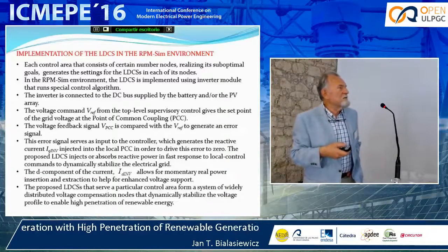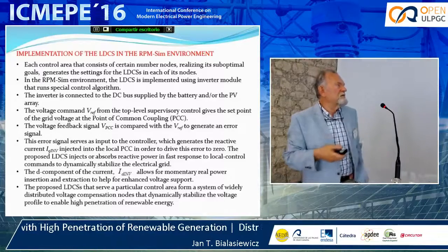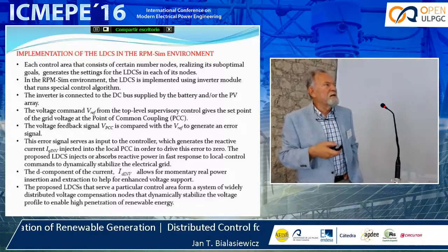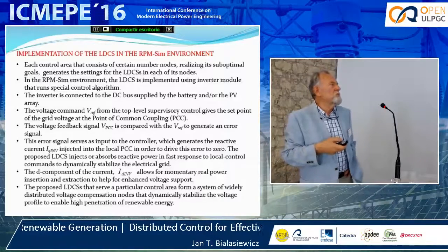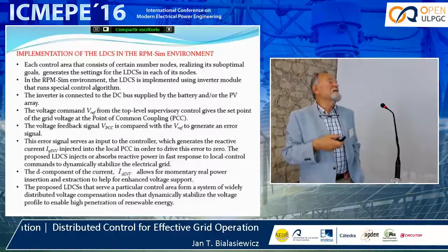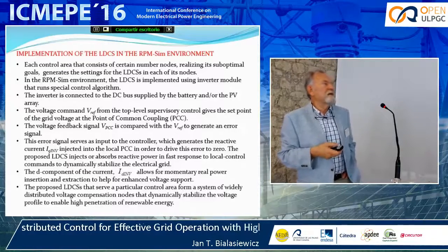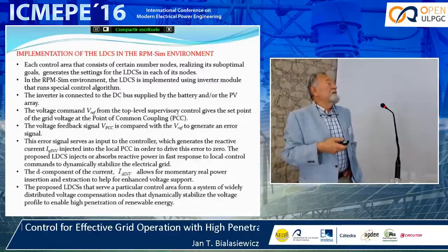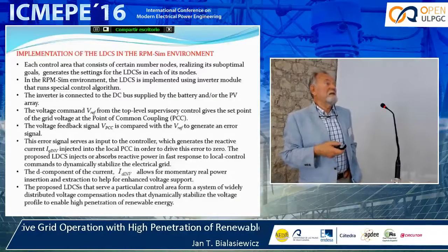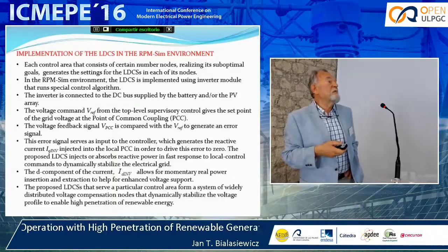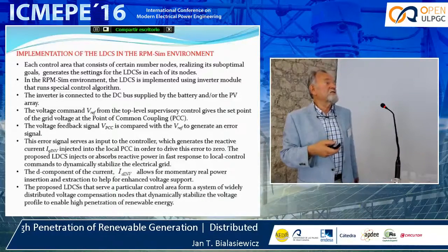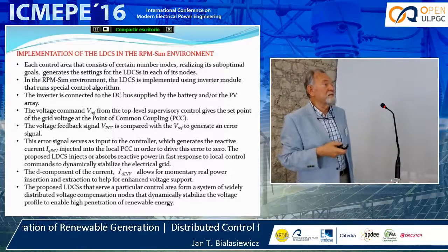The proposed LDCS injects or absorbs reactive power in fast response to local control commands to dynamically stabilize the electric grid. The D component of the current, ID inverter, allows for momentary real power insertion and extraction to help for enhanced voltage support.